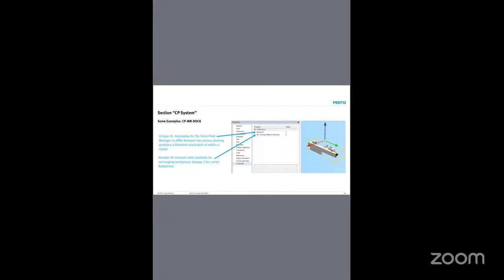So how is this docking working? Docking means the robot reaches the workpiece and properly aligns with the docking station. The fleet manager will check the station ID. The robot will dock properly, the conveyor belt will work properly, and then the workpiece is transferred. Once the transfer is completed, the robot will go to the next station.